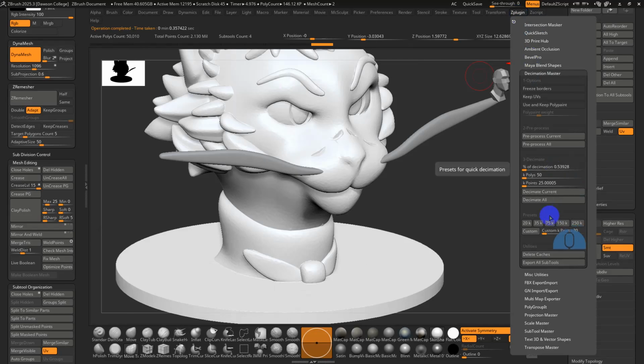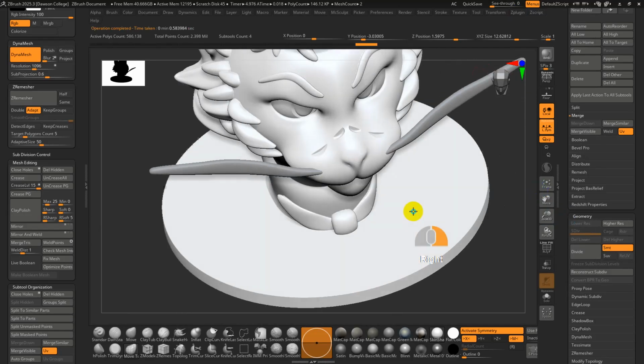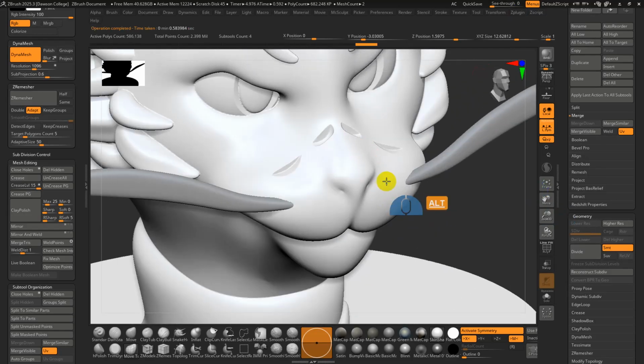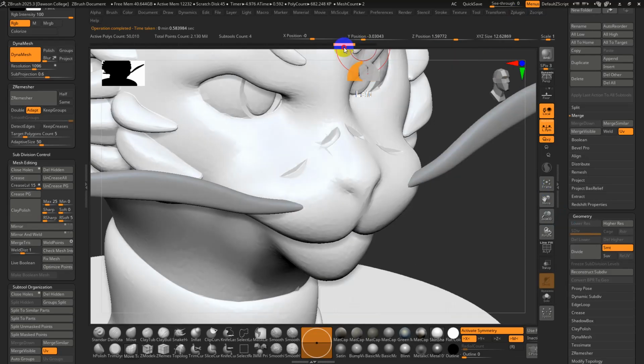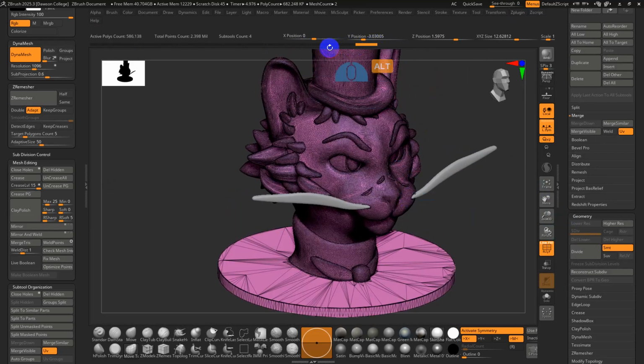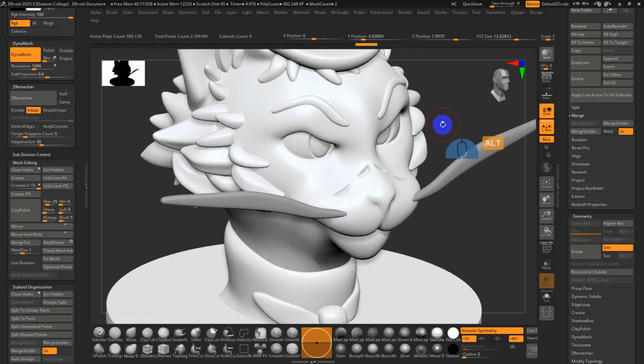I used to do this thing where I would undo, and I realized that's a mistake because you can actually just change the number here and hit decimate again, and it just quickly pops in. So this is now 500,000 polys, and if you take a look, it's actually not that different from the original, right? I mean, it looks practically the same. So it's a huge advantage to decimating, right? If you didn't have the wireframe on, you would almost detect no difference.